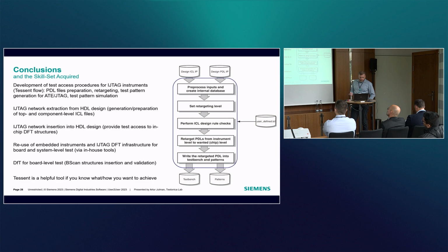Starting from development of test access procedures, of course, preparing PDL files, performing retargeting, performing test pattern generation, also retargeting for ATE and JTAG, and doing the simulation.